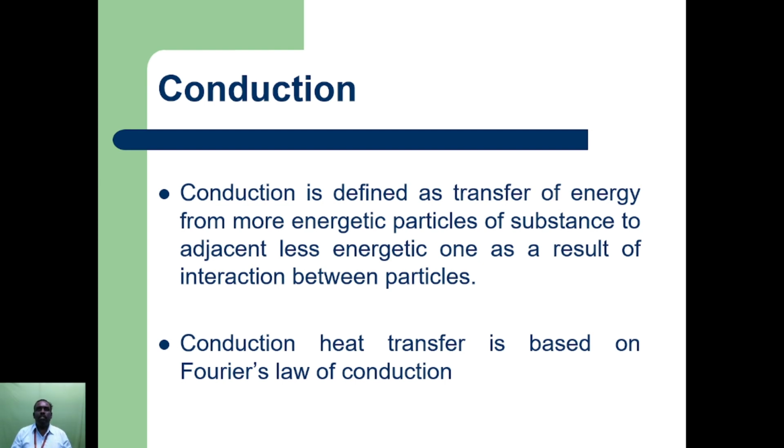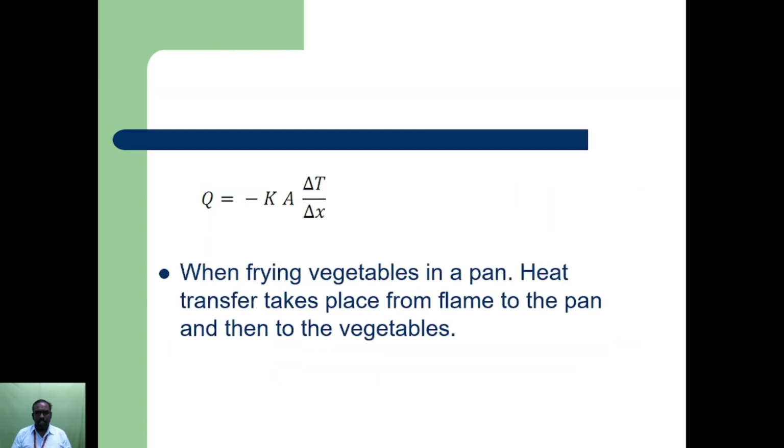As per the term, we are studying conduction in this subject. The transfer of energy from more energetic particles of a substance to adjacent less energetic ones as a result of interaction between particles, that is the meaning of conduction. That is Fourier. What is Fourier's law? Q equal to minus K A delta T by del X.